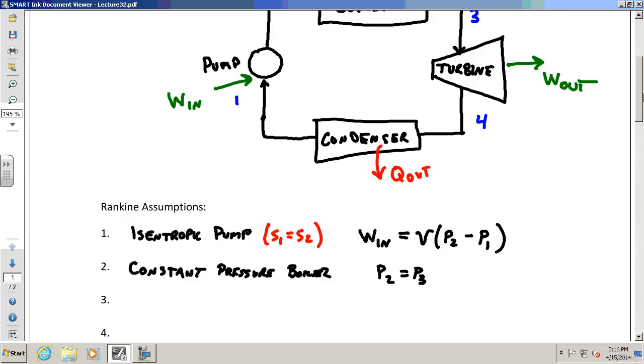Why not? If it's just an open container with the pipeline straight in, pipeline straight out, shouldn't it? Yeah, in theory, sure. But you can have a little bit of pressure build inside a boiler. It can happen, so it depends on how the process is done. I'm guessing it's small. Yeah, and you could have pressure loss in the piping. That actually is probably more common.